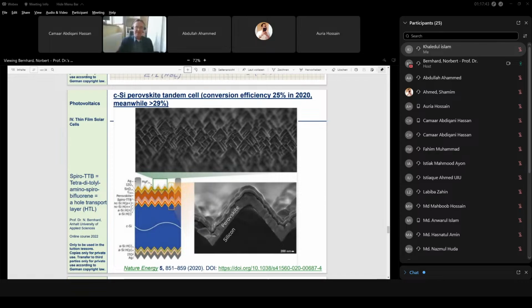The germanium part, of course, is in principle a wafer-based technology, but the others are just deposited by a metal organic CVD process, and therefore the III-V semiconductors, the gallium arsenide-based semiconductors, they are thin film technologies. And gallium arsenide, of course, is also a direct semiconductor.